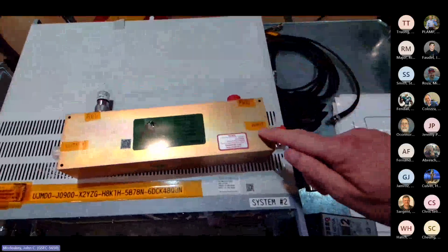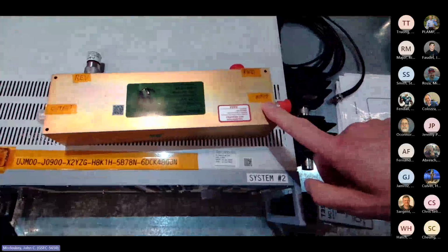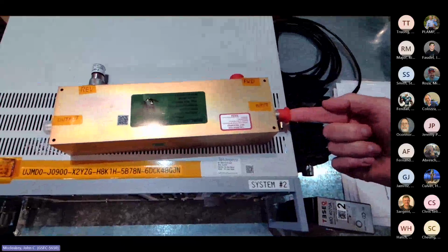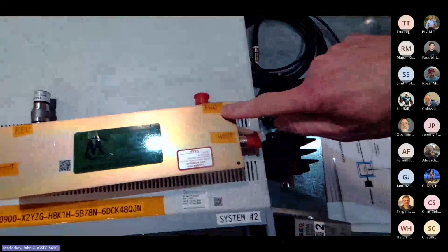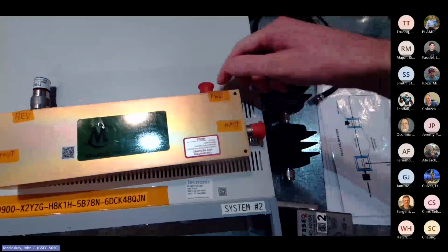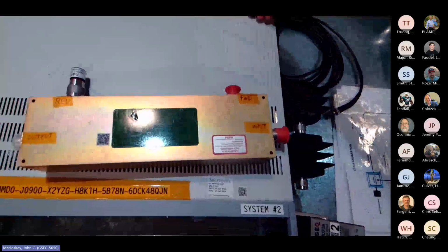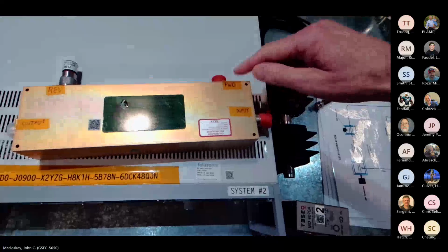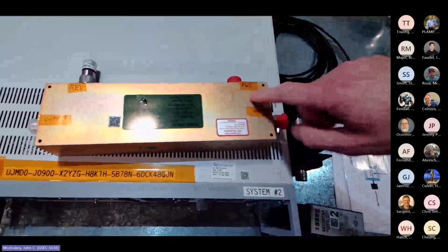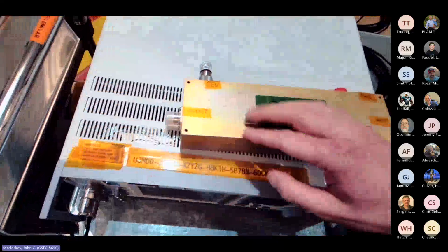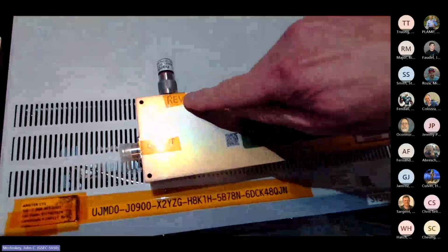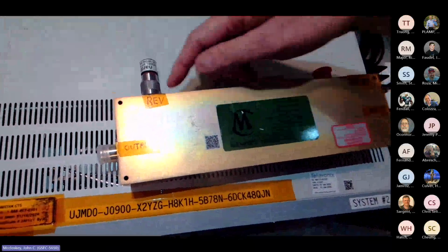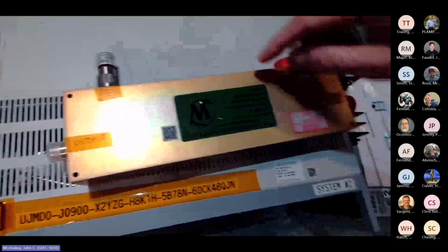The writing, at least for me to be able to read it, is right side up this way. So here's your input. You just put your signal in through this way. This is your forward power port. So you would tap off this point to go to any measurement device, spectrum analyzer, a scope, to measure the forward power. And then here's your output to go to the destination, to your load. And then there's also a reverse power port here. So if you're not using a port, you generally want to put a termination on it.